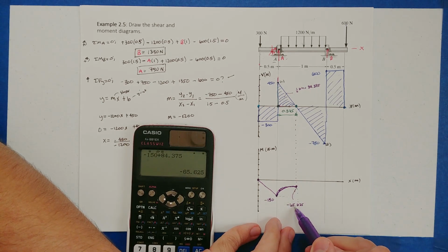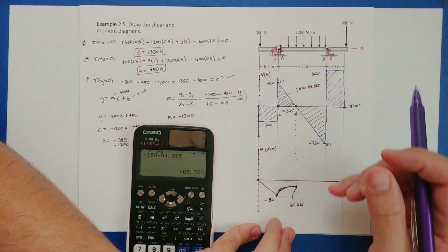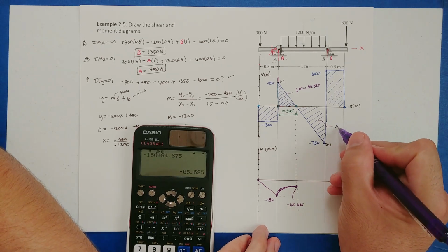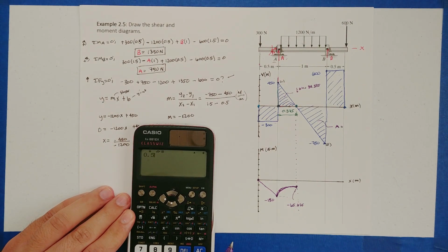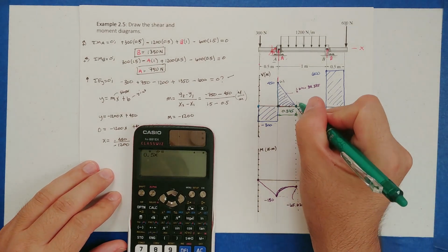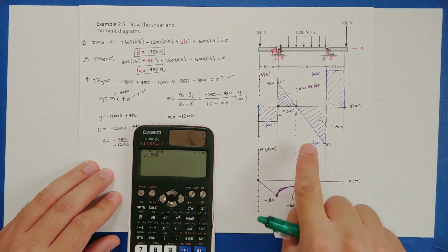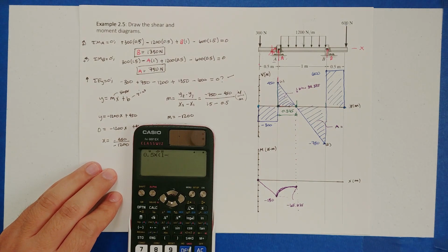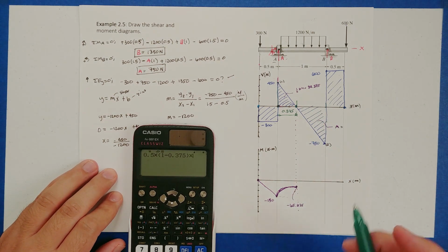So we're at minus 65.625. And then what happens? We get this other area. It's negative, so we're going to subtract it, right? This area over here is also a triangle. So the formula is going to be 1/2, or 0.5, times the base. What is this base? Well, this whole thing from here to here, if you remember, was 1 meter, but we already used up 0.375. So we're going to take 1 minus 0.375. That gives us this base over here, times the height.